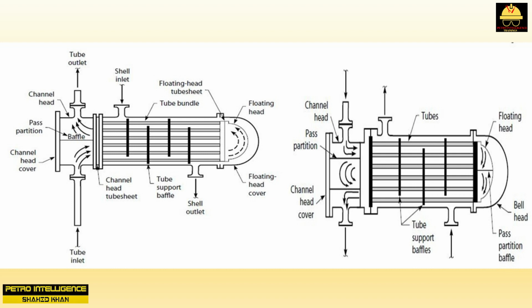That is fine. But what about pressure drop? When we convert a tube bundle from 2 to 4 passes, the pressure drop increases by a factor of 8. For example, assume that the 2-pass delta P was 5 psig. With the same flow, the 4-pass delta P would be 40 psig.